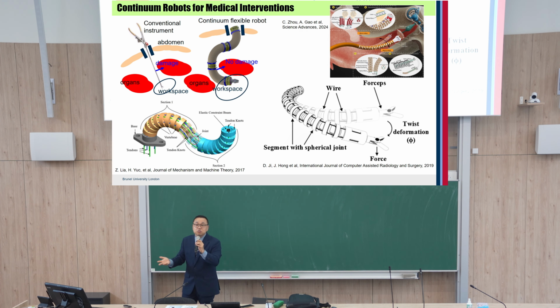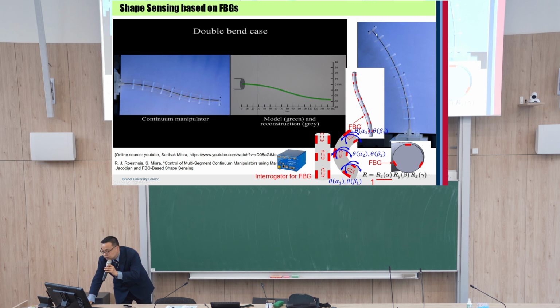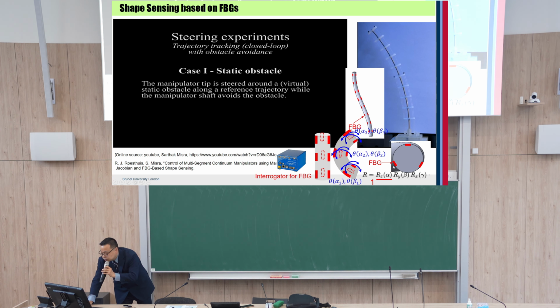Here. Do you remember I explained the strain gauge, right? There is also some not strain gauge. However, this FBG, the fiber Bragg grating, this sensor can really measure tiny deformation. Here on the core, this is some elastic material, and they mounted a bunch of these FBGs. Every section like this, they mounted 3.